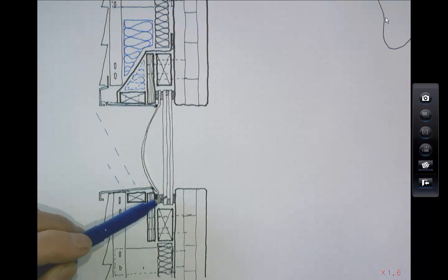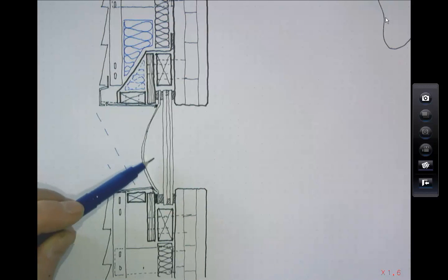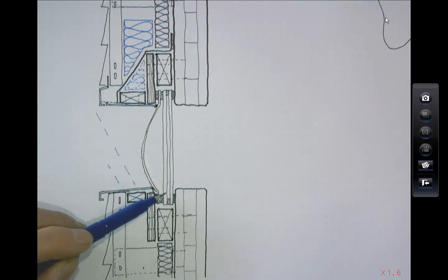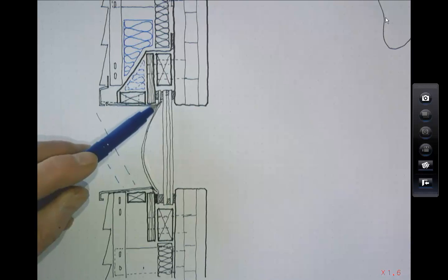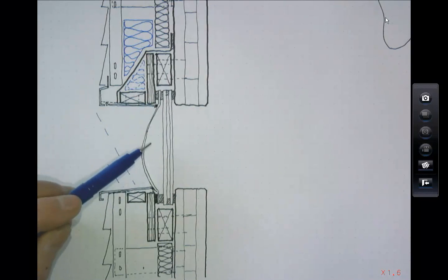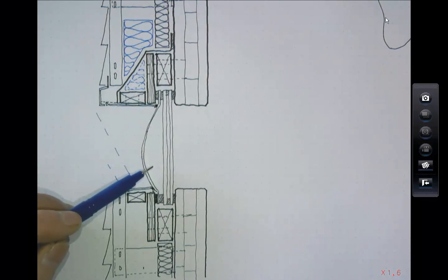You don't expect anything to get in there. It shouldn't leak. But this cavity in the glazing between the Cox Dome and the glass is something you're asking builders to put together on site. And the potential for that join there and that join there to leak, and you get condensation in here, is quite significant.